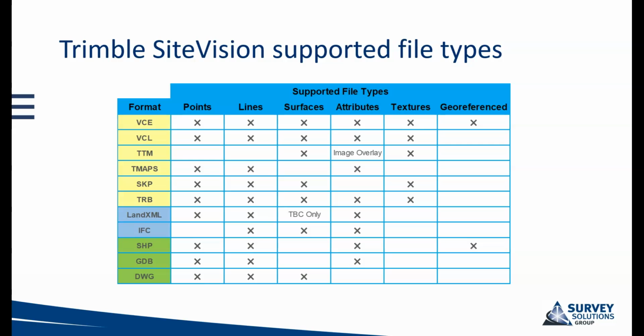In blue, two open industry formats, LandXML and IFC files. So with LandXML, these can be used to display survey data, surfaces, which, for the surfaces, require to be exported via TBC. If you want to visualize fully rendered models of 3D pipework from TBC, then this should also be exported as an XML file. We can support versions 2, 3 and 4 of IFC.